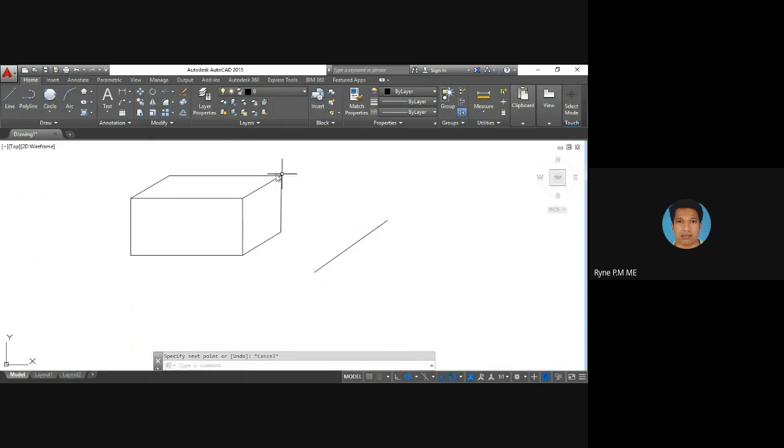Once more I'll show you. Select the line command, select the first point. Then at the rate, say the dimension is at the rate 45. Angle is less than, angle 35. So at the rate 45 angle 35. In that way you can type and draw inclined lines also.